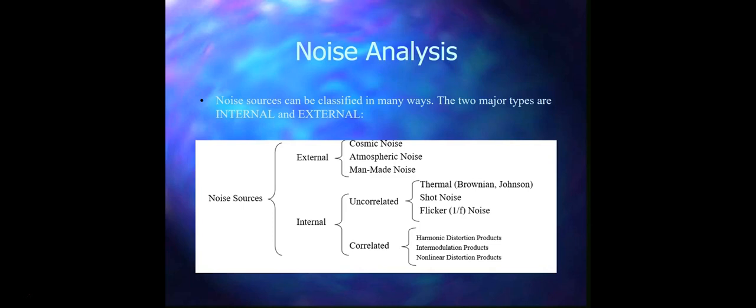Now we have shot noise. Shot noise occurs basically in electrical elements that have a PN junction, for example your BJT or FETs. Each charge carrier that crosses the PN junction in those kinds of devices introduces a momentary jump in the overall diode current.